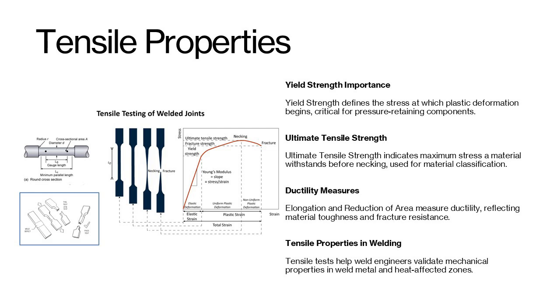Reduction of area, RA, is another indicator of ductility, revealing how much the cross-section shrinks at the fracture point. Inspectors must correlate these properties with design expectations. High YS prevents excessive deformation, adequate UTS maintains structural capacity, and good elongation ensures resilience against brittle behavior. By reviewing tensile results, weld engineers confirm that welding procedures produce acceptable mechanical properties across the weld metal and heat-affected zones. These properties together help determine whether a material can safely endure service loads.